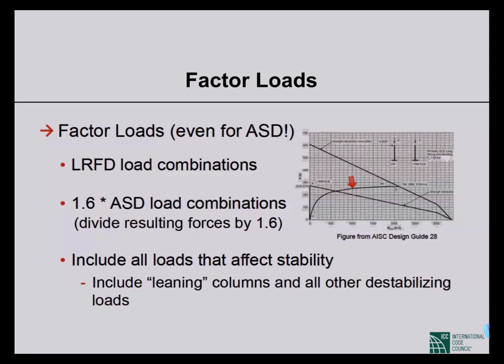So we have to combine all these combinations. We cannot run separately for dead load and separately for lateral loads. We cannot do that. We have to combine them, and that will be one case for running, because all the loads, both lateral load and gravity load, must be present to take the P delta effect into account. So that's very important.